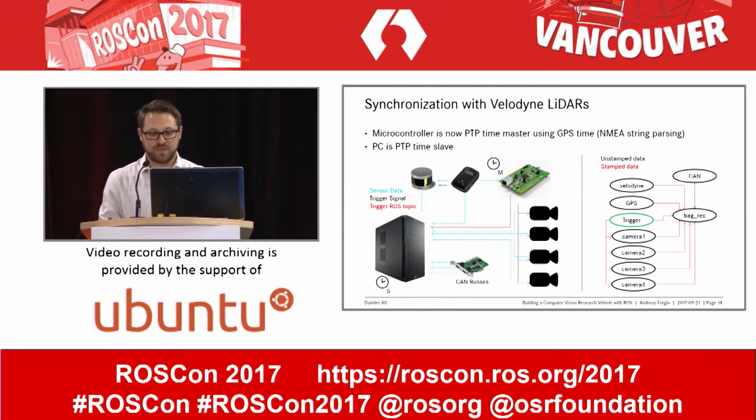But we can go one step further and add Velodyne LiDARs to the scene. The Velodyne itself has a solution for timestamping using a GPS sensor and the PPS, pulse per second trigger system, in conjunction with an NMEA string. And in our setup, we can use the GPS time as a reference time. The microcontroller then becomes the PTP master and transfers the time to the host, which all will be GPS time. And in the end, we have all sensors living in the same time reference.